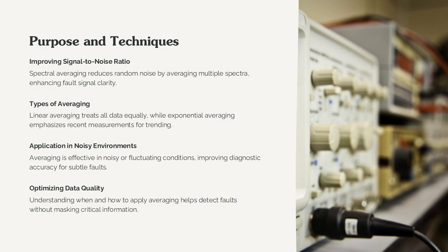Proper application of spectral averaging enhances diagnostic accuracy, making it easier to identify subtle fault signatures such as bearing defects or gear wear. Analysts should understand when and how to apply averaging to optimize data quality without masking critical information.